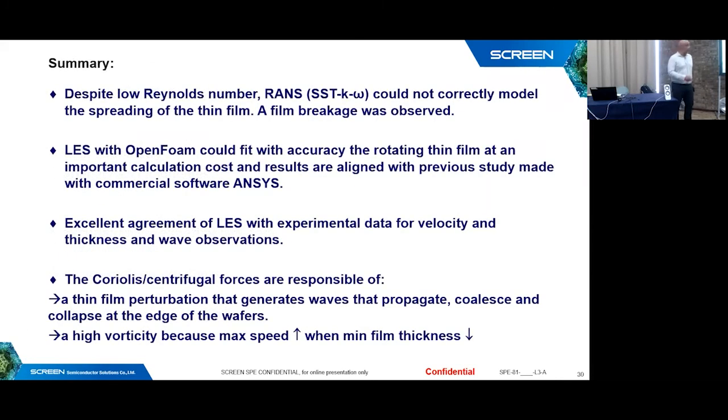The summary of my talk is that despite the low Reynolds number, we could see that the RANS model couldn't work. We have many problems of film breakage and a too high estimation of the speed. The LES with OpenFOAM could fit for us.